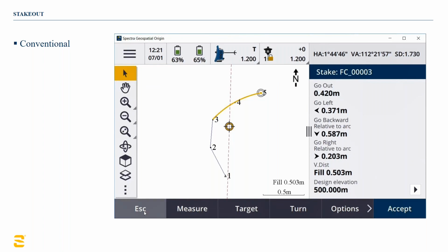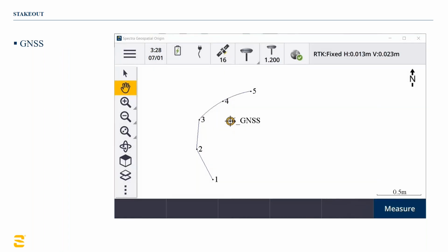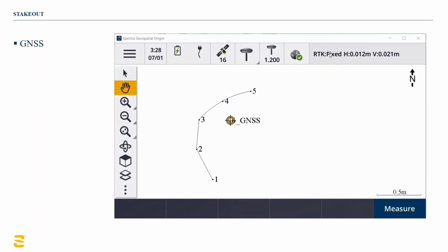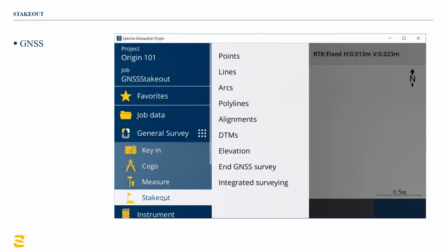Okay, so what am I showing you now? I'm done with total station. GNSS is very similar, but different. I won't belabor it, but I will run through these in the same way. I'm in a fixed solution, tracking 17 satellites. Got my HA in there at 1.2. Code for me that it's not a real number. I'm going to stake out a point.